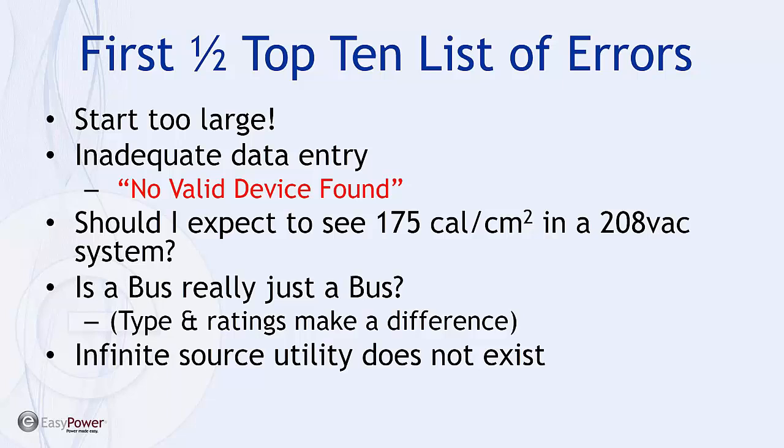And this goes to the fact that the IEEE guidelines and NFPA 70E both refer to the fact that below 125 kVA source and voltages less than 240 volts, there's a very low possibility of Arc Flash blast or instant Arc Flash hazard. And so the results are conservative based upon using the IEEE model.